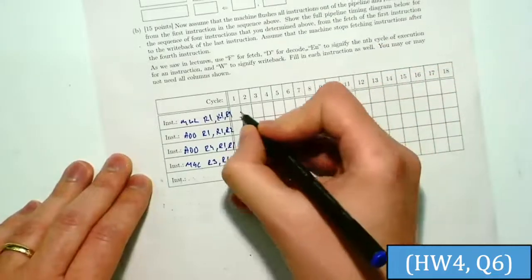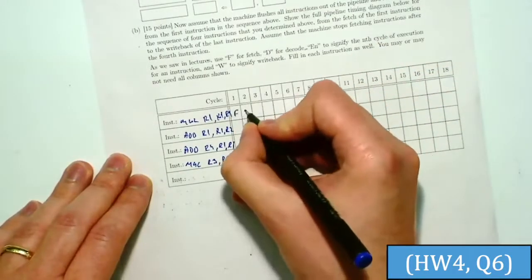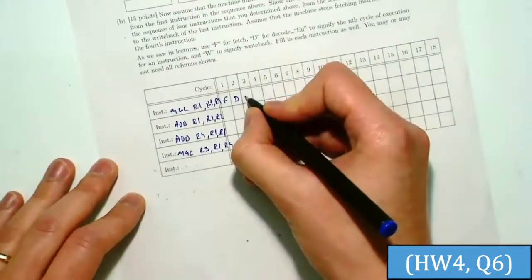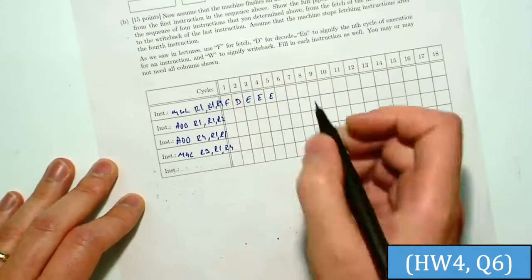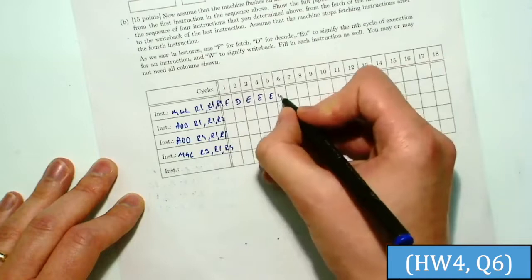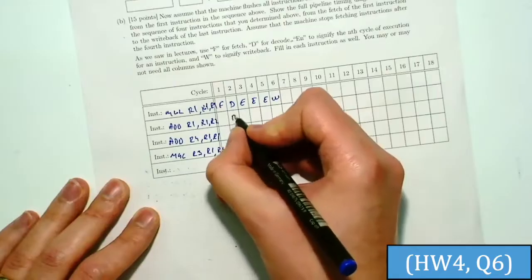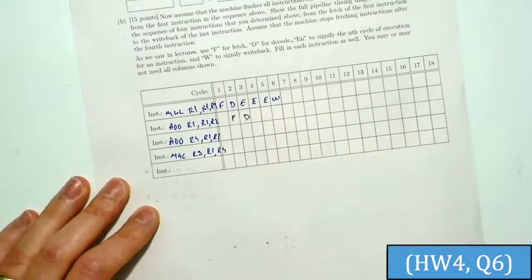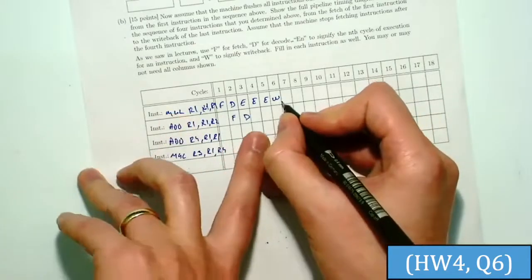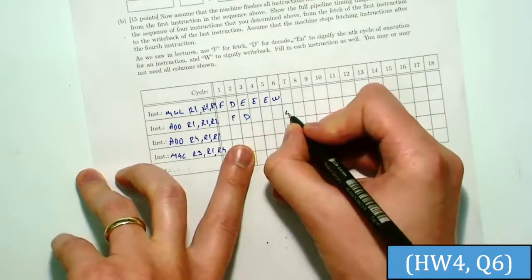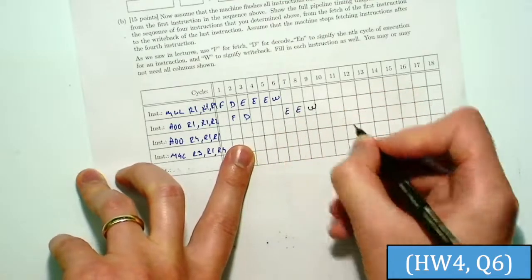So we know that this processor has a fetch stage of 1 cycle. It has decode. Multiplication instructions are executing in 3 cycles. So we will have 3 execute stages in here. And we have write back. Okay, so this is the first instruction. The second instruction, we can fetch here. We can decode and dispatch here. But since it has dependency, it has to wait until the end of the write stage to execute. So it will start executing here and will do write back.